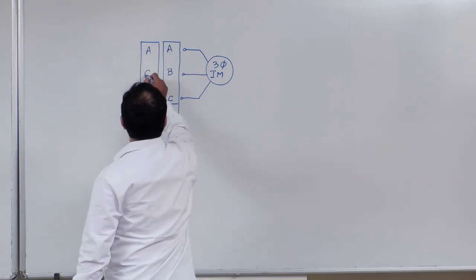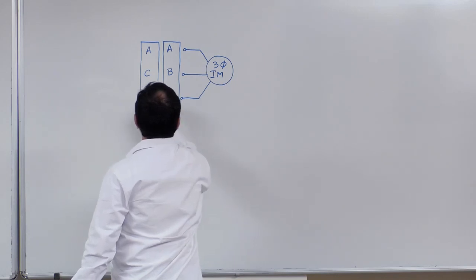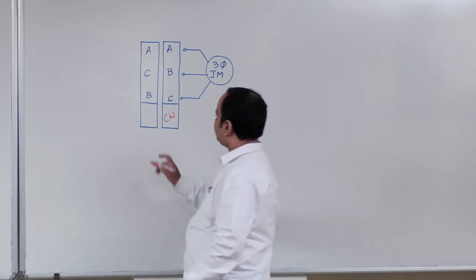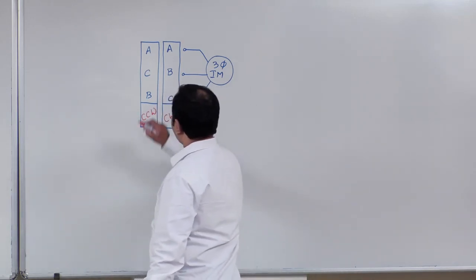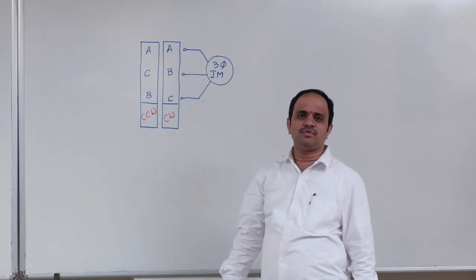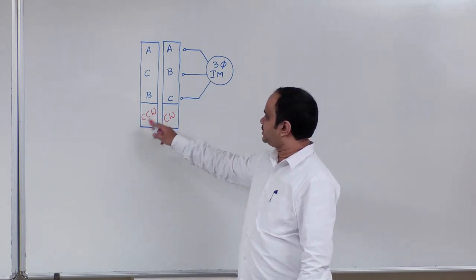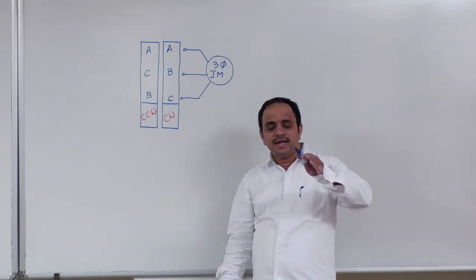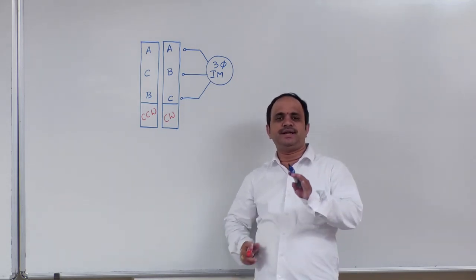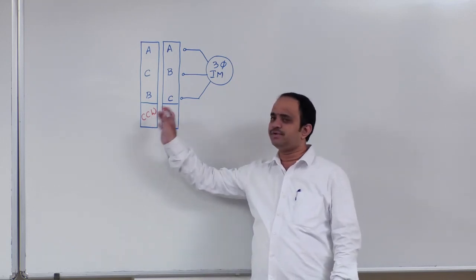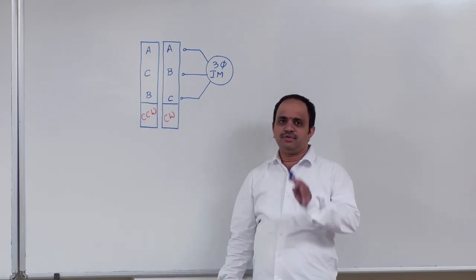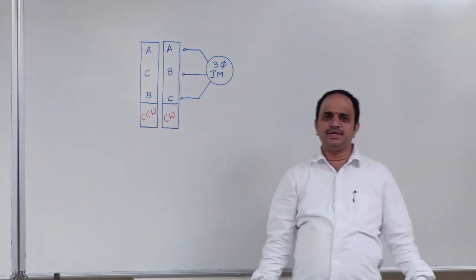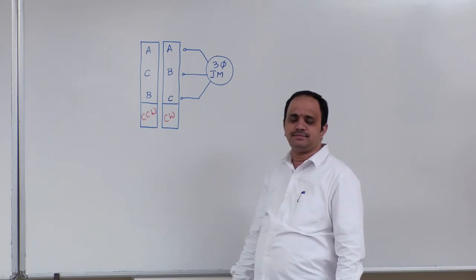What we can do here is change the phase sequence to ACB. Therefore, the machine will now rotate in the counterclockwise direction. If you really want to change the direction of rotation, that is the procedure: you can interchange the phase sequence.